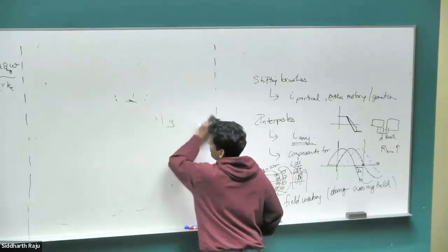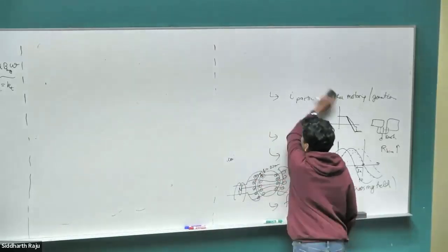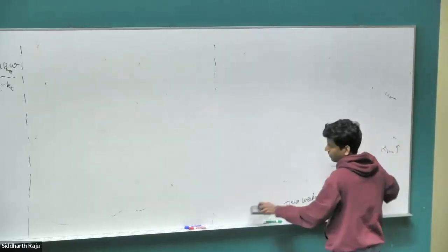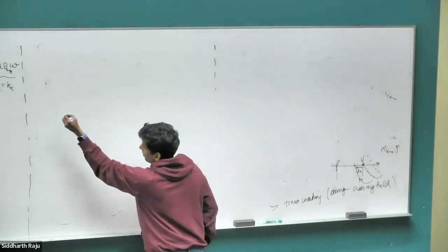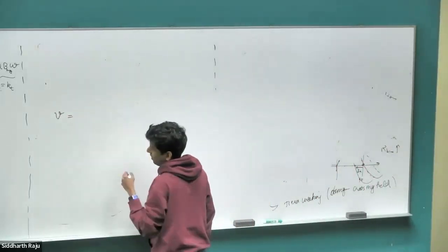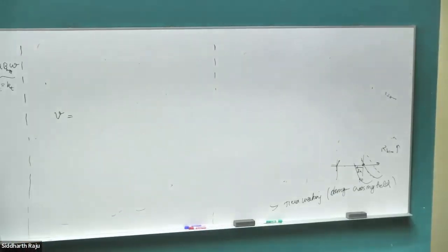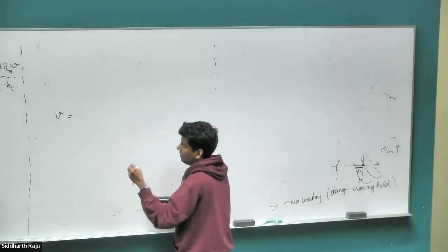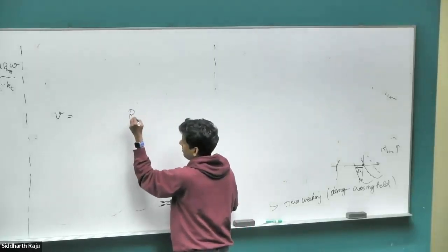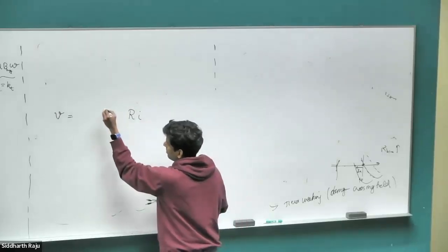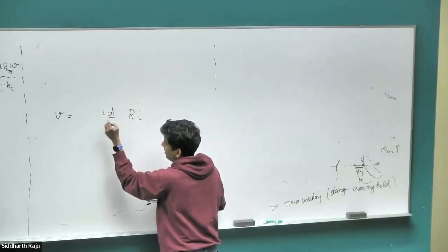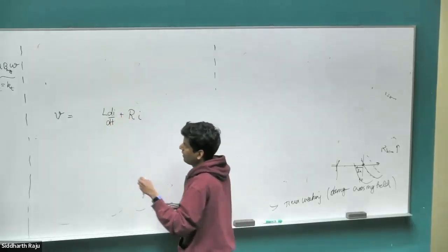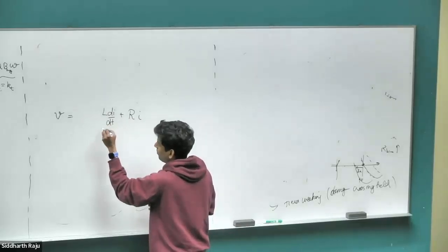We have everything here that we need to know to control this motor going forward. So our electrical system equation is going to be, we apply some voltage across the terminal of this motor. So V is the voltage that I apply here. And then some of the voltage is going to get dropped in the resistance, right? R times I. Some of it is going to be the L dI by dt. Current flowing through, because there's a whole bunch of coil on an iron core, it's going to have quite a bit of inductance, as we'll look at when we estimate the parameters for the motor.